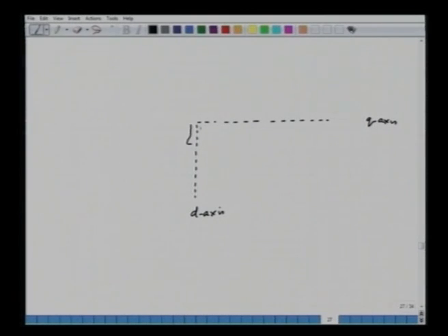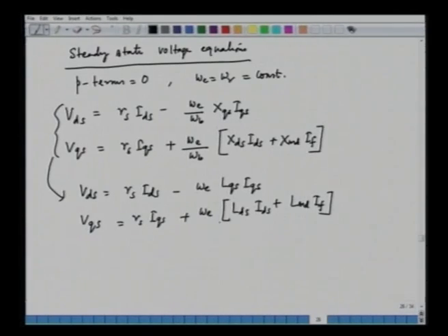We have the field in the d axis, the field pole, and the field current IF is in the d axis. We can show that to be IF here, this is a right angle. And then what we will do here, we will first write down the q axis induced EMFs. We have this term LMD IF into omega E, which is the same as the field induced EMF. So, we can say it is the same as EF.